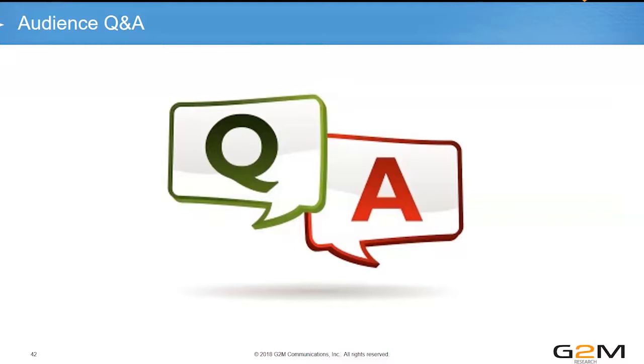Excellent. If I could give a counter answer, because I've thought the same sort of thing, wow, EDSFF is just going to dominate the world. The only problem I see with that is you're still going to have spinning disks. We've been trying to get rid of them forever, but they stay alive. And if you ever want to have any kind of hybrid system, it's so much easier to design a system that just supports the 2.5-inch drive form factor. And that's where I think the U.2 is going to live for a little while longer, until we can completely get rid of the spinning rust. Once the spinning rust is gone, then I think we can eliminate the U.2.